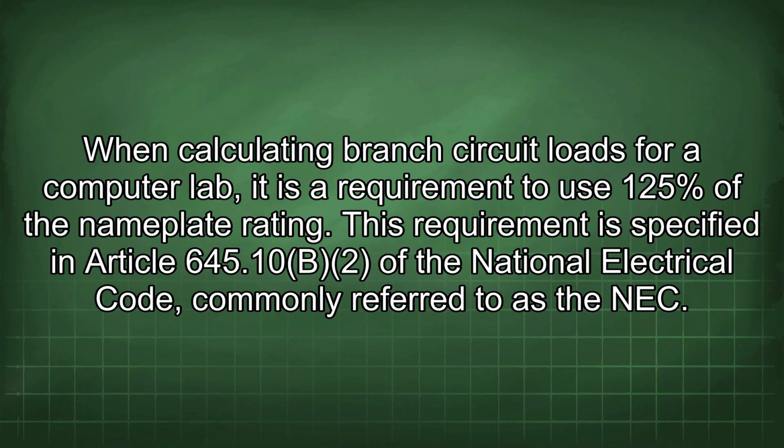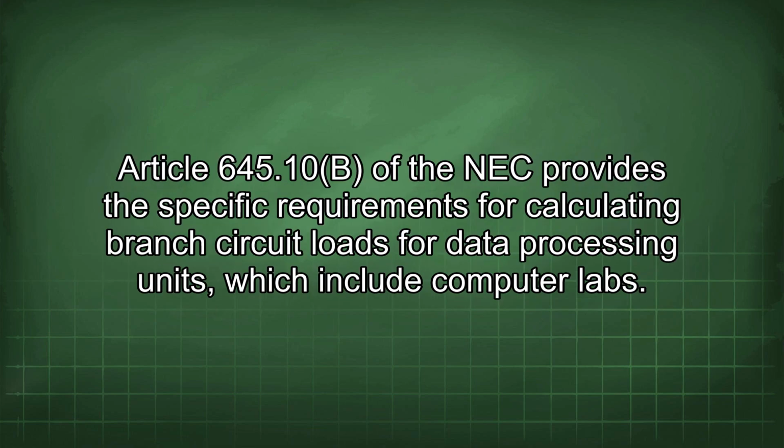When calculating branch circuit loads for a computer lab, it is a requirement to use 125% of the nameplate rating. This requirement is specified in Article 645.10(B)(2) of the National Electrical Code, commonly referred to as the NEC. Article 645.10(B) of the NEC provides the specific requirements for calculating branch circuit loads for data processing units, which include computer